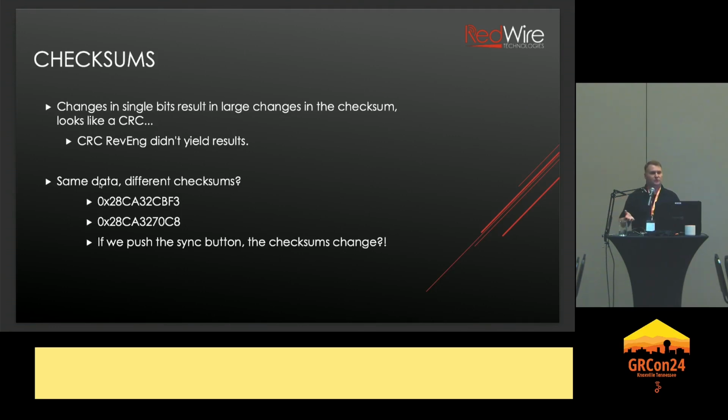So my next assumption was, okay, it's some sort of an XOR mask, or some other checksum being applied, and I started collecting packets. Then I ran into another problem. You can see I have 2 packets up there. The packet type and the temperature data are all the same, but they have different checksums. That one really confused me as to how you would possibly get it wrong. So, do I have something else going on there?